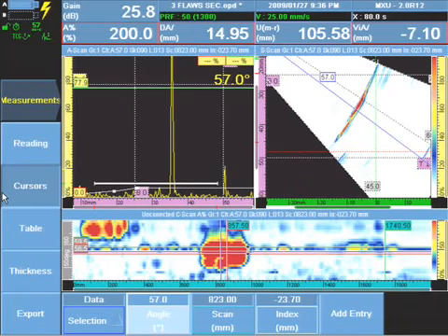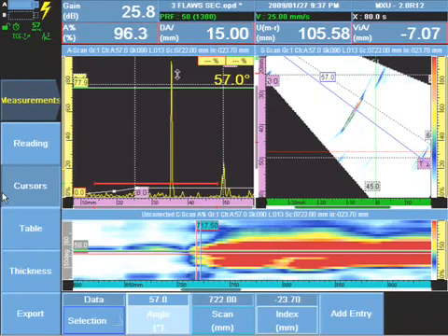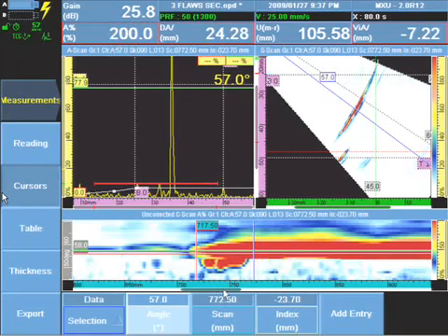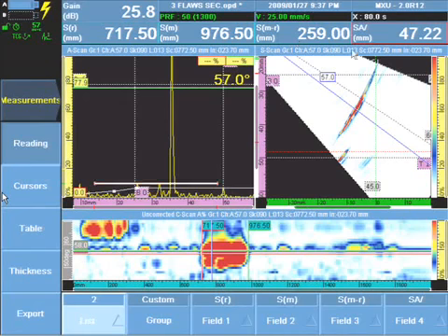The length of the flaw is recorded on the C-scan either by doing a 3 or 6 dB drop on the color palette, or using the data cursor and the amplitude reading to take a digital number for our 6, 3 dB drop, or whatever the code in the procedure requires. The delta between these two cursors on the scan axis is the length of our flaw.